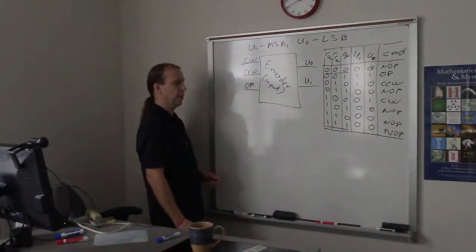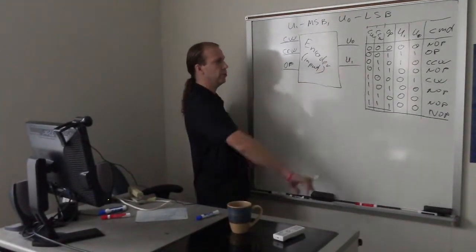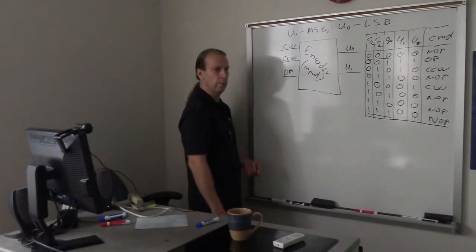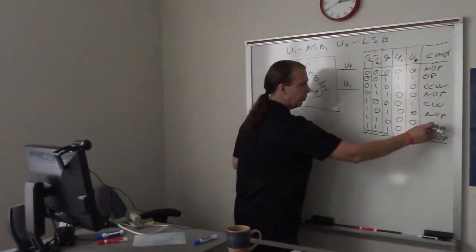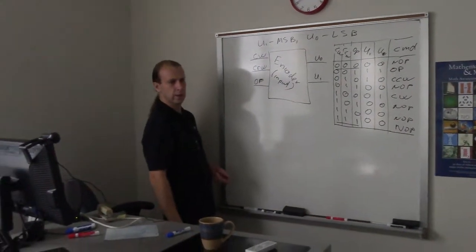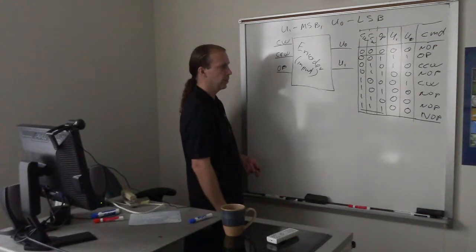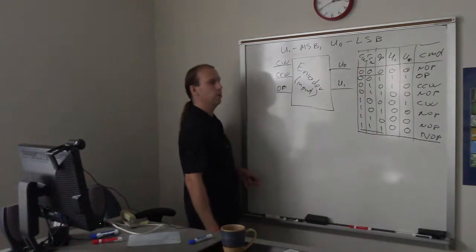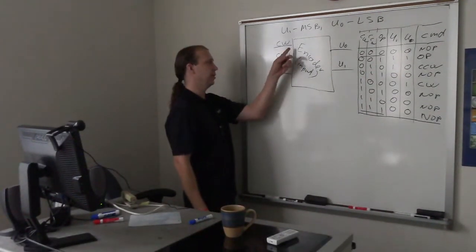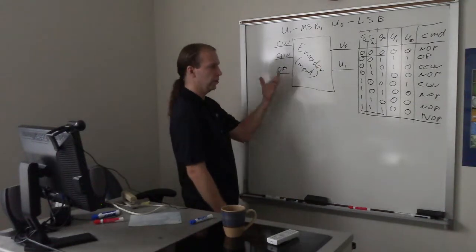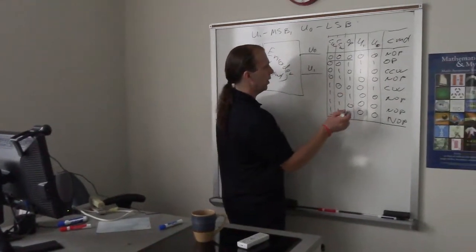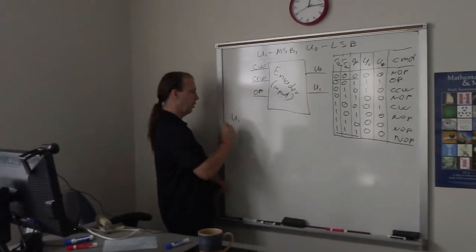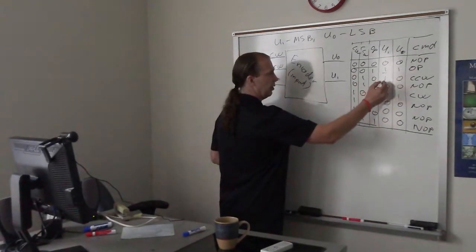So that's our table, and now we want to optimize it. Actually, we do not optimize the input encoder truth table, but later on we are going to use those no operations to optimize the excitation function for the triggers. What we are missing now is how this particular signal will be driven with respect to these three inputs. In other words, we're interested in logic, and we can think of the logic by evaluating the truth table. For example, U1 is equal to 1 here and here.